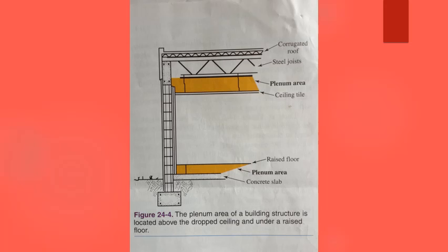When fiber optic cable is installed in plenum areas, the installation usually falls under the jurisdiction of the National Electric Code. The NEC has strict regulations about the type of insulation that can be used on the outer covering of fiber optic cables installed in plenum areas.